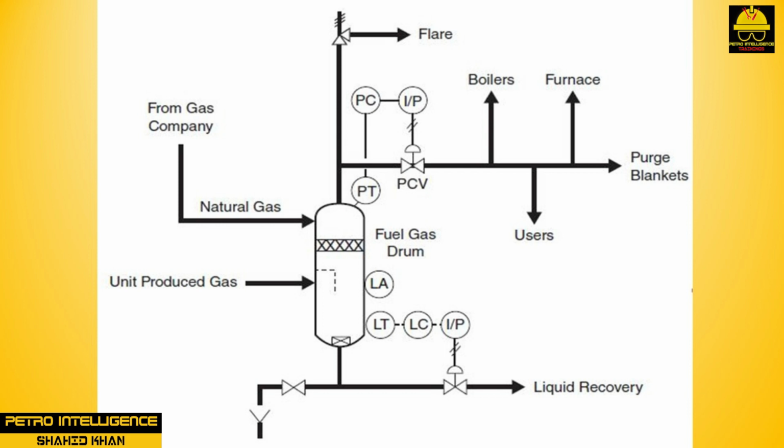Fuel gas required is typically produced internally during normal unit operations. During a startup mode or emergency mode, where no internal fuel gas is available, gas is imported. The imported gas is measured in a meter station before entering the unit. During normal operation, any excess fuel gas produced is exported by a compressor system.